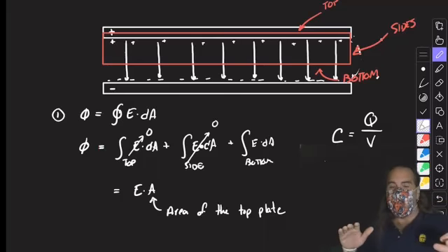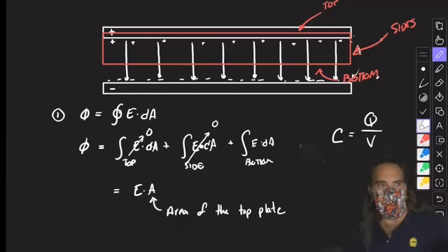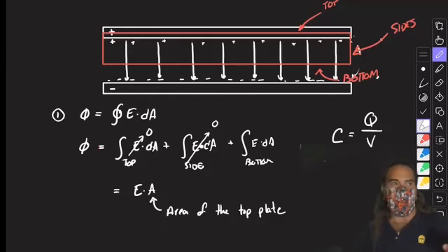Okay, you have to understand, when I say that the top plate and the bottom plate are very close together compared to the size of the plate, I'm not screwing around. Real capacitors use basically an oxidation process to put a single layer of atoms on one plate and then bond that to the bottom plate. So they are very big compared to their separation distance, since they are separated by just a couple of atoms. So you follow that idea there? So when we talk about the fact that the plates are very big compared to their separation distance, I am not even exaggerating a small amount. We're talking about two plates that are really close together.